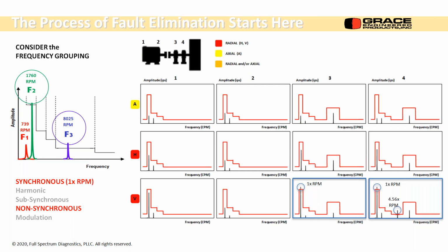The problem with vibration analysis is the peak's constantly moving around. So the alarm levels, it might get into a different alarm level. They might get close to a natural frequency and amplify it. And you might have certain conditions that you can't run just because there are vibration problems when you run there. It just makes it a little harder.